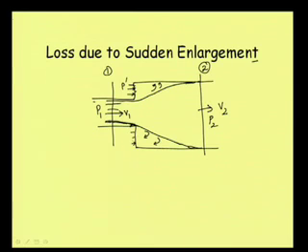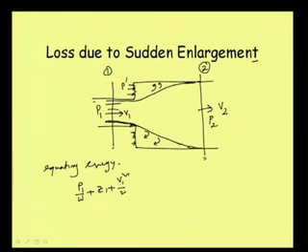Well, now if we write the energy equation between this point and that point, equating energy, we can write P1 by W plus Z1 plus, in general, V1 square by twice g. But as we are talking about a very small section, from here to here, the Z value will in fact be equal, because this distance is not that much.